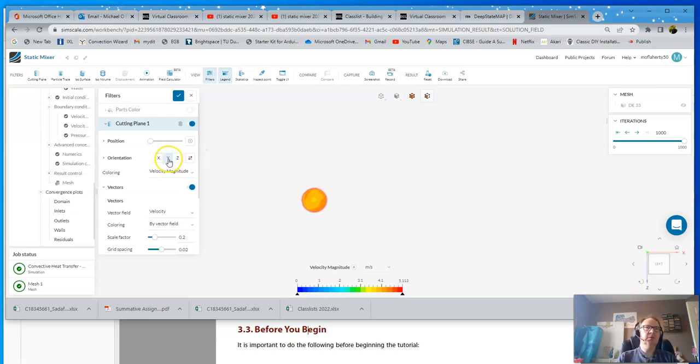And let's see what we can also do. It'll also print out all the statistics for that plane. Then, cutting plane 1, average velocity is 4.18 meters per second. Now you have 2 points with 2 meters per second and 2 meters per second. Average is about nearly 4 meters per second. Some slight error there possibly, but that would be remedied by making the grid finer, putting in more cells.